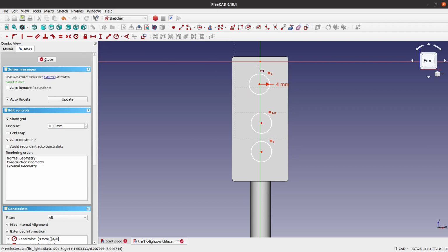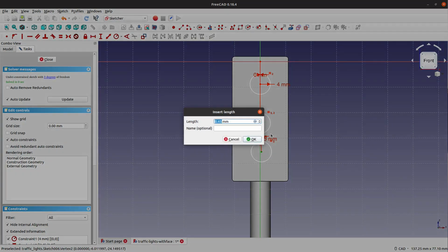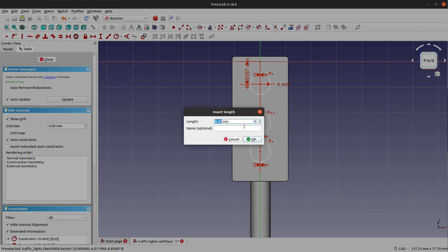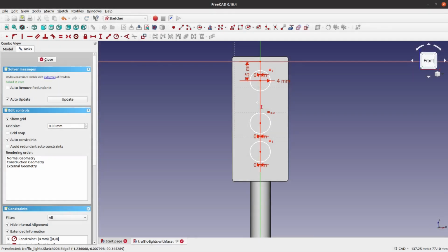Make these line up against this point, and we can do the same for the others. We can do them relative to that one, now we've set that one, or we can do them relative to the top. We can set this top one a distance of 7.5mm, which is the distance from the top of the body parts, not including this overlap, down to the centre of that.